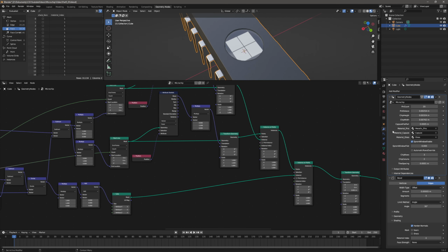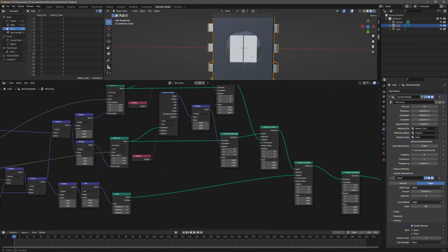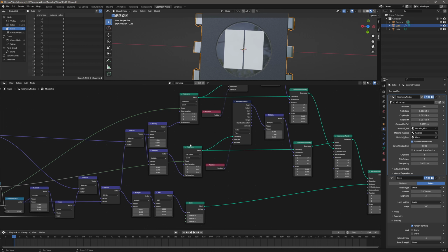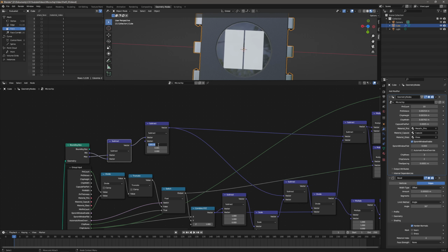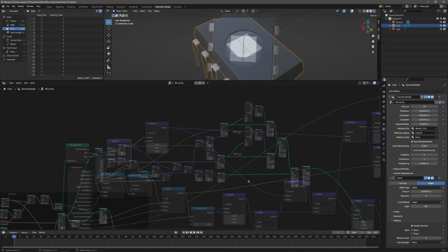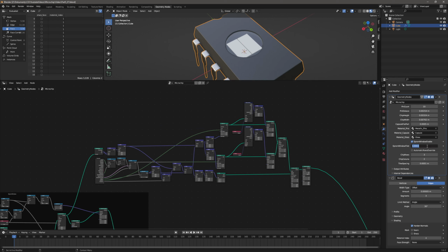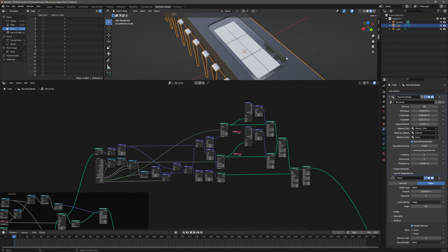Let's actually enable the automatic rows, change it for example to 10, and we have it nicely inside. Maybe change it to 1.3 millimeters on both the axes to be really sure that it stays inside 1.4 millimeters. Okay, I will do it like that. Well, let's just return the fillet to something normal so that we don't have the circular window, and let's enlarge the chip a little bit.